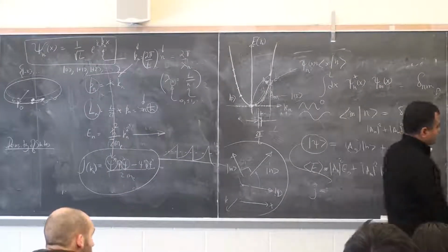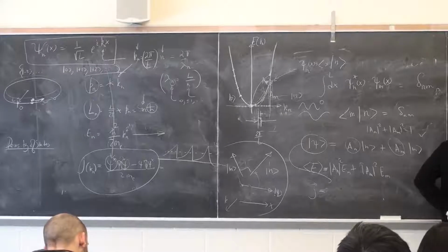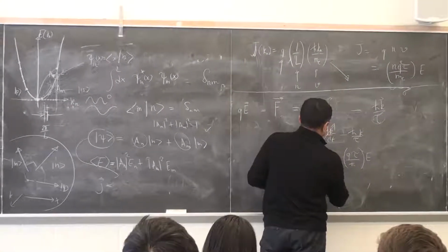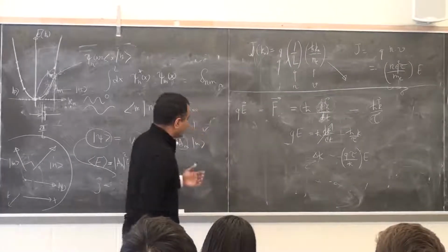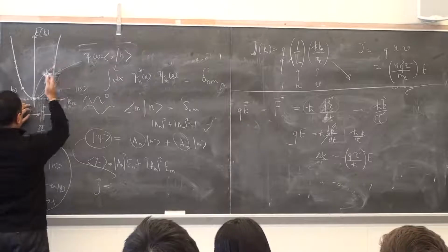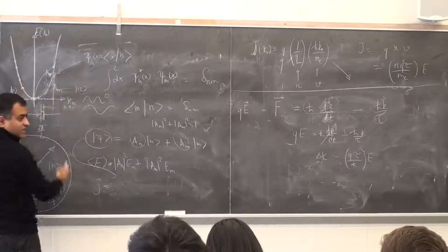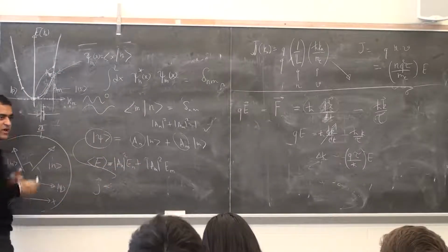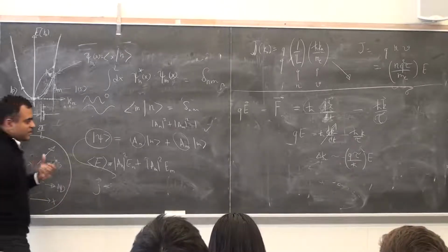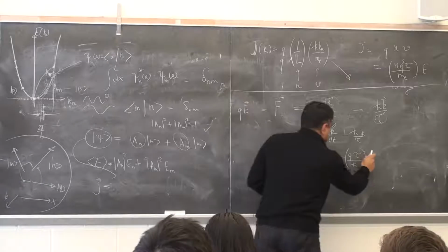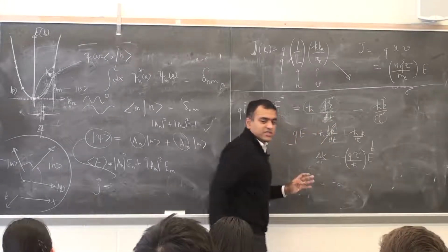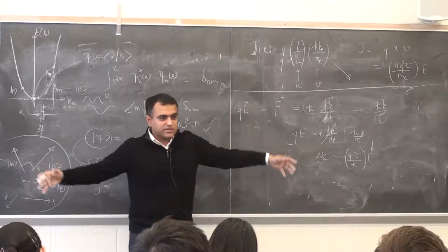So this is the drift term. And right, okay, so this is essentially what you get, that the electron momentum, on an average, would be delta k, because it's not going to be unbound. It's bound by this quantity. Does that make sense? I mean, it doesn't go much beyond that term, right? And as you increase the electric field, obviously this k increases. It samples a little bit more of the k space because of that.